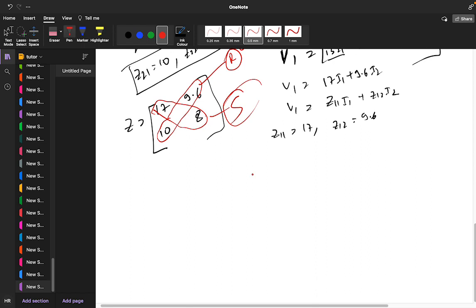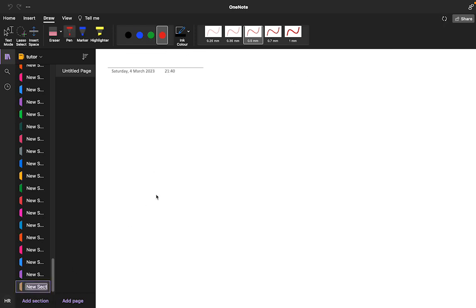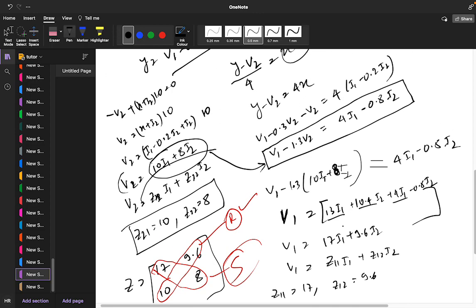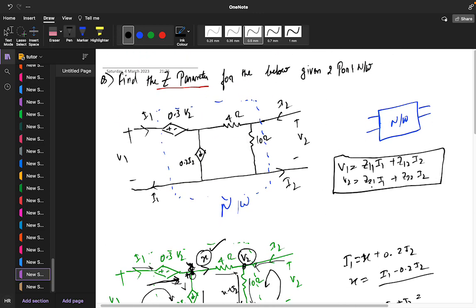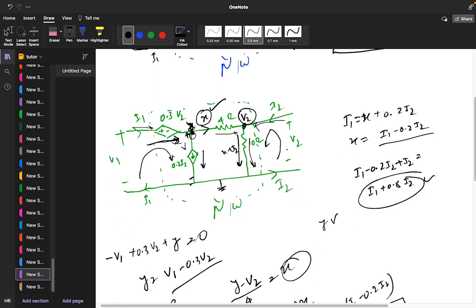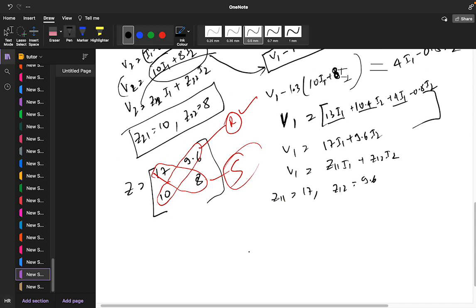Okay, so this two port network, another question. Write another question for a two port network. See, it's very easy. Either you can solve it like this, as I told you, make this circuit and write the equations. Z11 is equal to what? V1 by I1. Put I2 equal to 0 and solve the equation to get the ratio V1 by I1. Or you can make equations in this form and simply calculate all the values. It depends upon you how you solve.